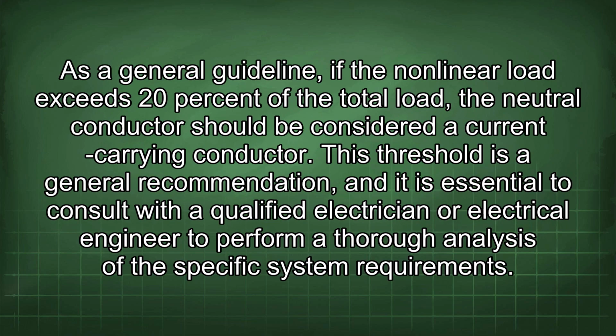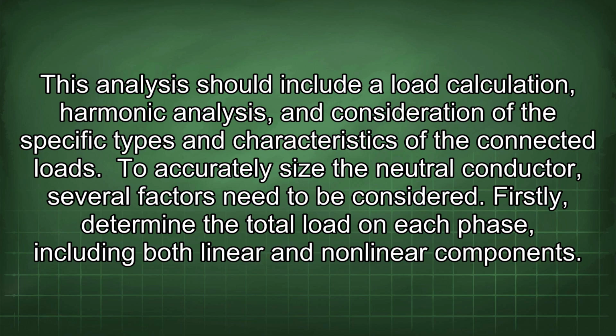As a general guideline, if the nonlinear load exceeds 20% of the total load, the neutral conductor should be considered a current-carrying conductor. This threshold is a general recommendation, and it is essential to consult with a qualified electrician or electrical engineer to perform a thorough analysis of the specific system requirements. This analysis should include a load calculation, harmonic analysis, and consideration of the specific types and characteristics of the connected loads. To accurately size the neutral conductor, several factors need to be considered.